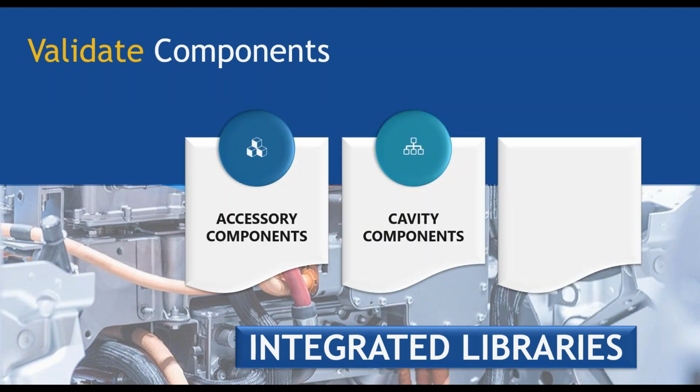Through the use of Capital's integrated library, a harness manufacturer can add automation to the component validation process. Once the connector part number is selected, the tool will add any mandatory accessory components like back shells and locks. This eliminates the need to repeatedly refer back to the manufacturer specs to check if you are missing a component or if they are compatible.